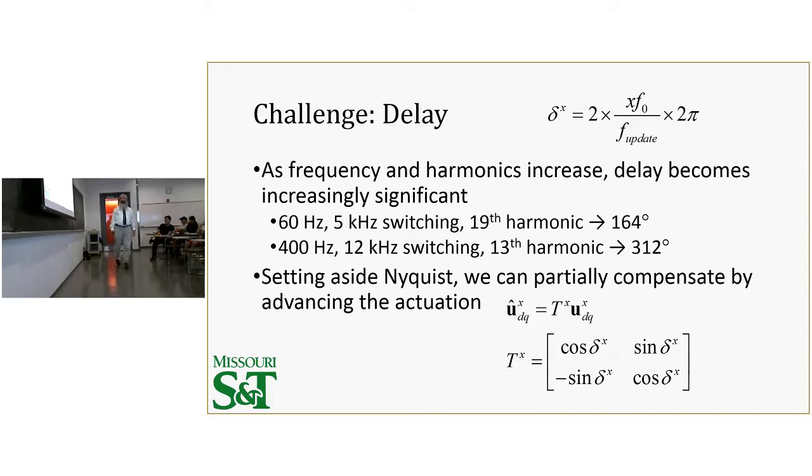Okay, and what that does is helps recover some of the phase margin that you would otherwise lose in your control loop. So I kept finding that I couldn't stabilize my control loop until I added in this phase advance, and that recovered enough phase that I could make a stable controller.